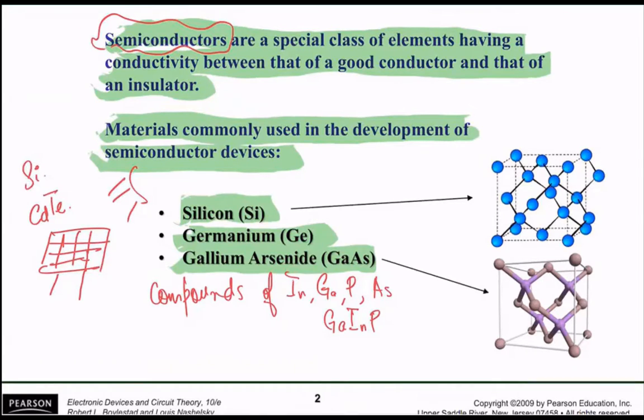If you see a panel which looks bluish in color, that's probably silicon polycrystalline, kind of like this color right over here. If you see a chocolate color solar panel, it's probably cadmium telluride, which looks brown. And depending upon how much light there is, sometimes it may just look black from a distance. So these are the important semiconductor materials which are widely used.